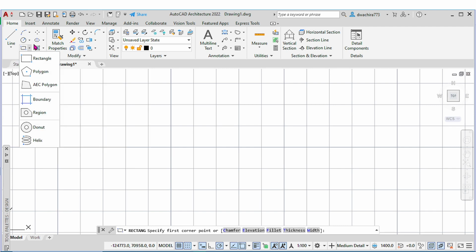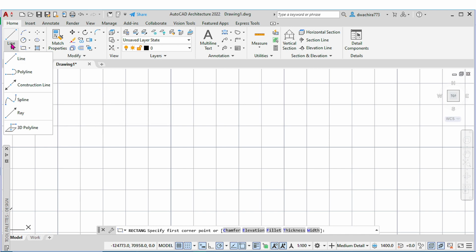Now, the tooltip has below the description, just before the expansion, some line with information written in capital letters, just above the place F1 for help. You can note that there is place F1 for help, so above that, we have rectangle. That particular rectangle is actually the command line shortcut, or you can use that option of typing that name to activate the rectangle tool. Of course, that will be the same for any object.